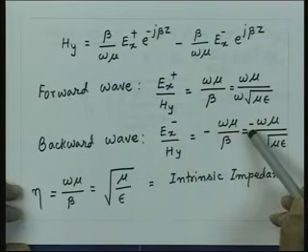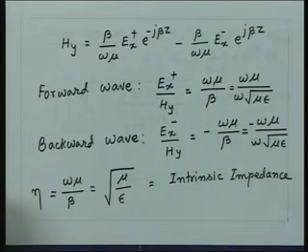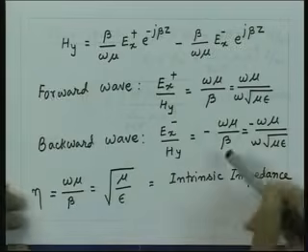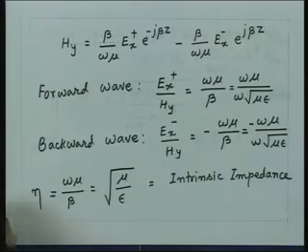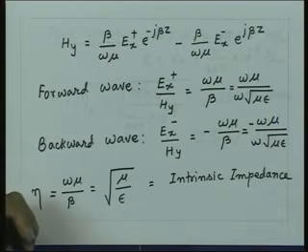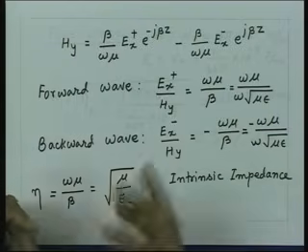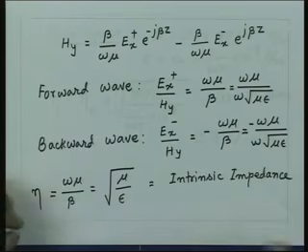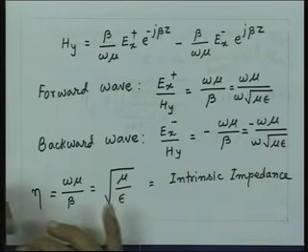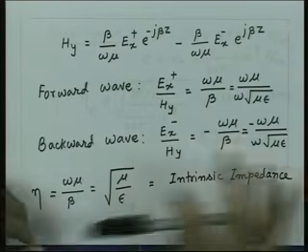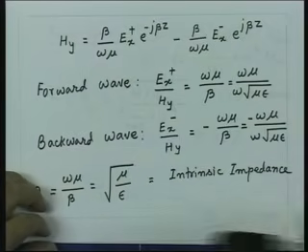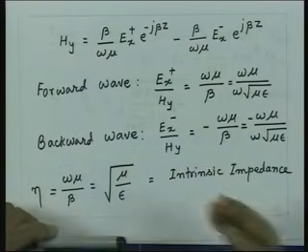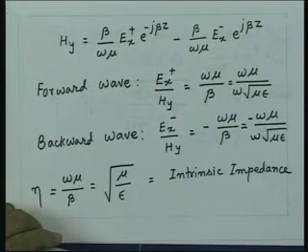However, there is a negative sign here, and if you remember, a similar thing we had for the transmission line case also: a forward travelling wave used to see an impedance which is the characteristic impedance, but the backward travelling wave used to see the negative of the characteristic impedance. That time we had understood that if the power is travelling backwards, it is as if the power is supplied to the generator, which is equivalent to a negative resistance.